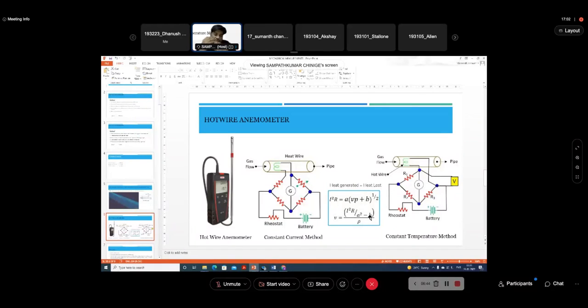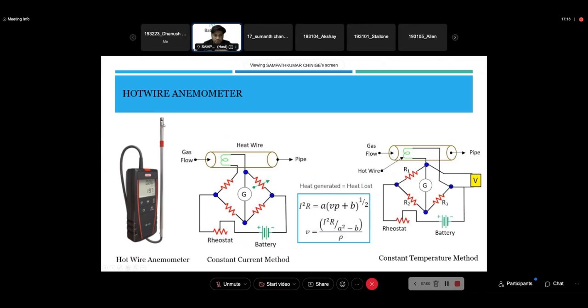But our main aim is, you can see over here you have a hot wire anemometer, which is basically one dimensional, which comes around 20 to 60,000. You can see there is an opening over here, right? I hope you are able to see this, right? You are seeing an opening over here, exactly here. So this opening is kept at the place where you want to take the measurement, and there is a small wire which is connected, and this antenna-like thing can be extended, the telescopic stand we call it. So it can be extended to whatever distance, and the digital value will directly come over here.